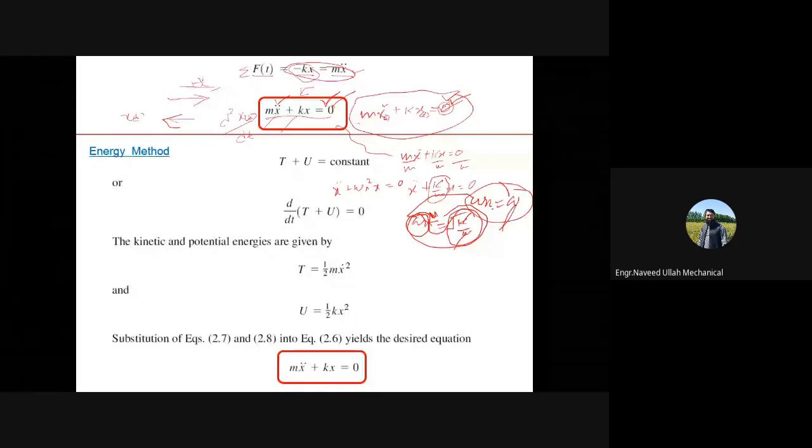There are some conditions, because you need to operate that particular machine at that particular speed. So this means that this is actually a known quantity, but this is not in your hand. So somehow, if there is some coincidence of these two, then we have other techniques like the dynamic vibration absorber etc., with which we can avoid this condition.